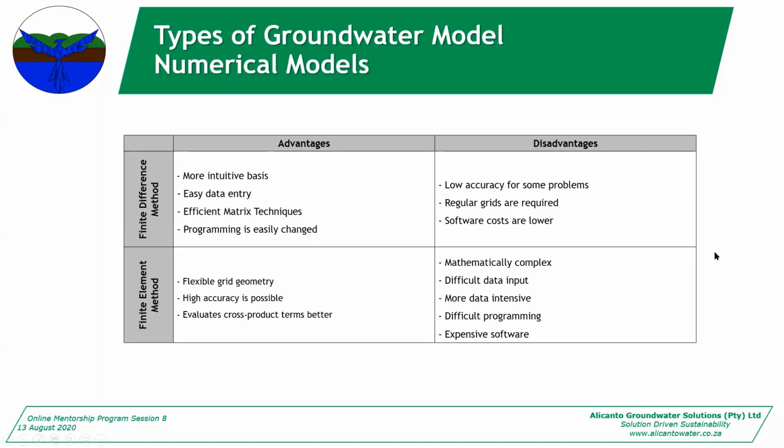For finite element, your advantages are the flexible grid geometry, so you can fit your grids a lot better to your environment. You get a high accuracy possible with a finite element model, such as a FEFLOW model, and it evaluates your cross product terms better.